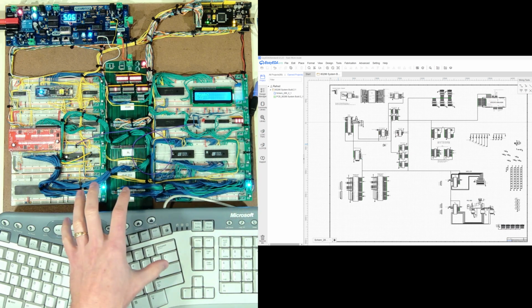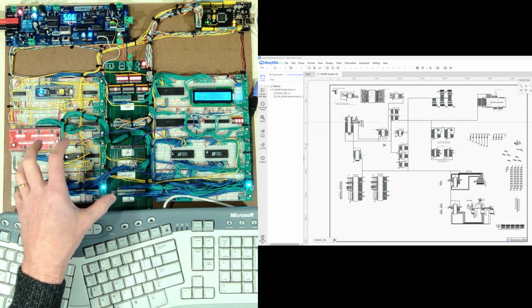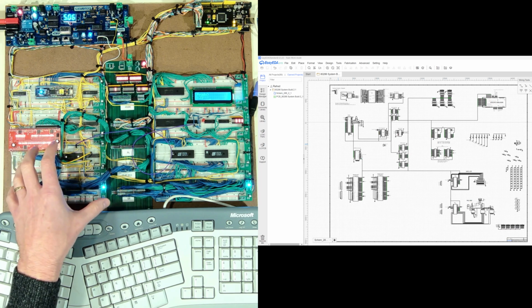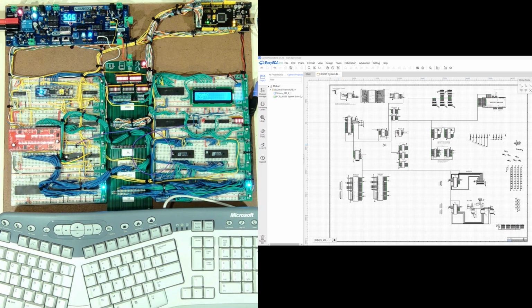I'm just simply processing and saying, okay, I acknowledge I've got the interrupt, and for now I'm just throwing exclamation points out over there, regardless of which key I press. And you'll see that there's three that show up, and that's because every time I press a key, there's actually 3 interrupts that come through. And I'll address that later in some further assembly coding.